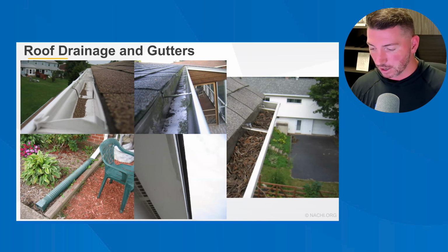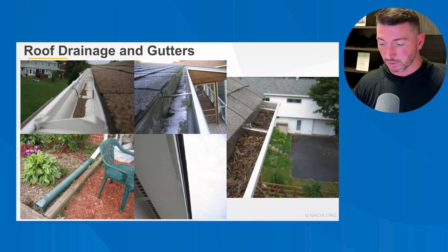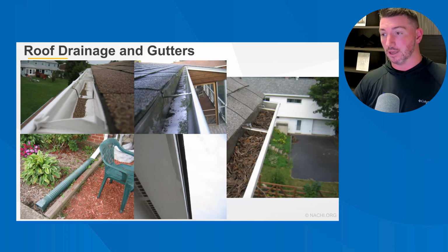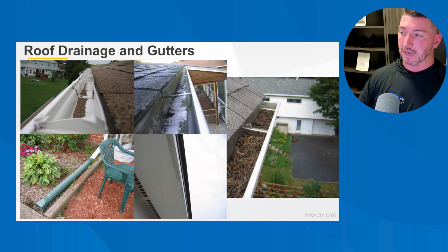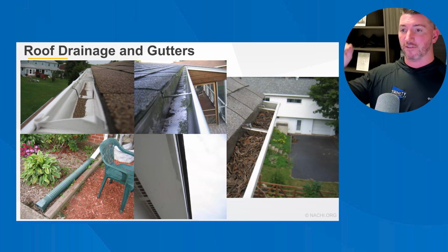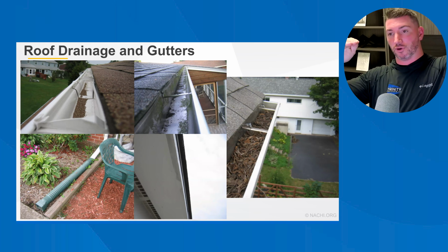It's not uncommon to see gutters installed too low on the fascia or to see roof coverings projecting too far over the gutters. In both cases, this may lead to water overshooting the gutters completely. So that's one of your main things. I don't see gutters that are not pitched properly as often. It's gutters that are installed too low on the fascia, if you sort of project the angle of that roof.